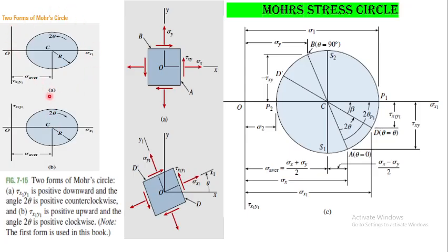We shall be considering this approach of the Mohr stress circle as it is fundamental, because when we rotate our angle theta in the Mohr circle, it will be anti-clockwise, which matches our previous main assumption that anti-clockwise angles are positive. Now, to understand the Mohr stress circle, remember that these two axes are not geometric axes. These are shear axes.